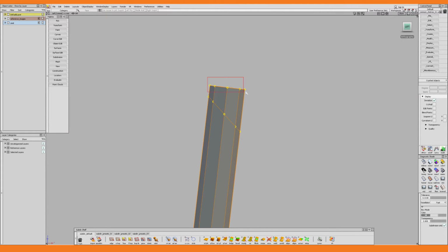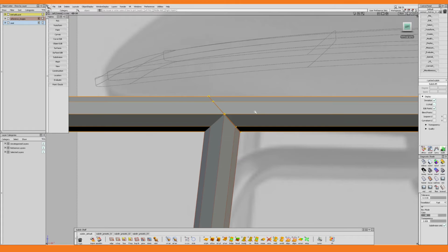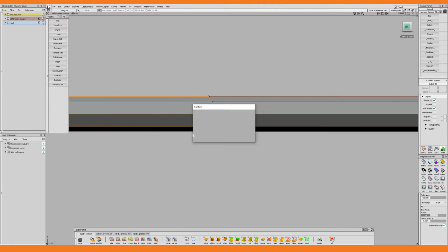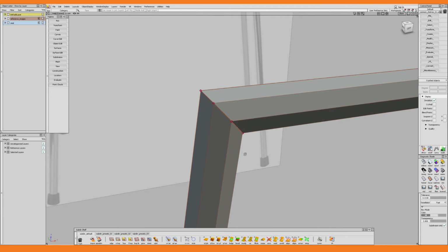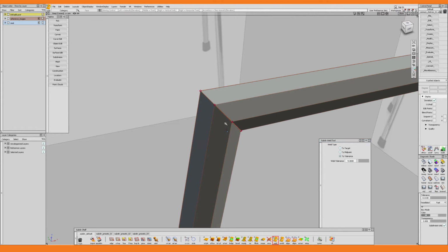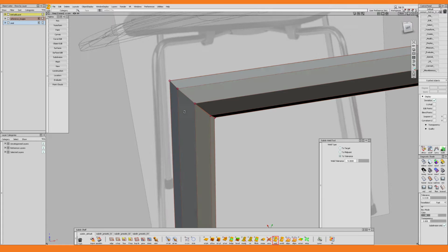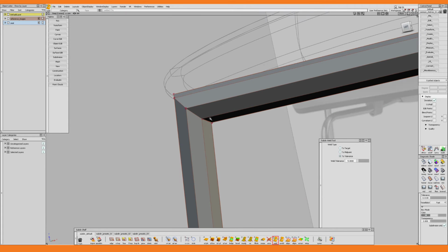And now I can easily just select all the faces I don't need and get rid of them. And I've noticed that I can only cut through half a cylinder, so that's why I deleted the other half before performing the cut. Now I enter the weld tool, and I set the tolerance to a large number. Notice that I'm welding edges this time, instead of vertices.